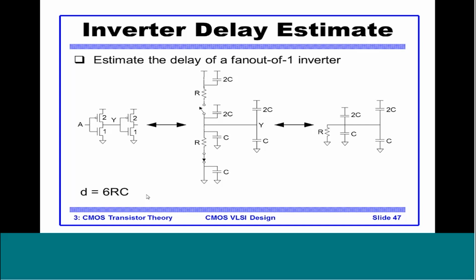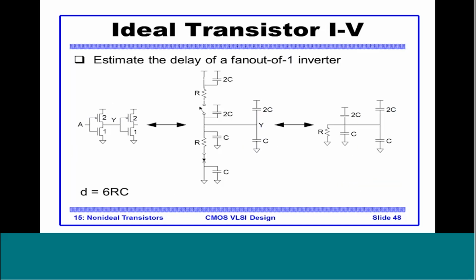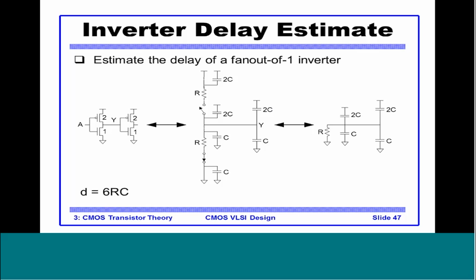This is useful to compare different types of circuit designs. Now what I would request is that all of you go back and estimate the delay of a few basic designs, let's say 2 input NAND gate, 2 input AND gate. We will explore this area in detail when we come to the calculation of propagation delay using logical effort. This will be very useful there.